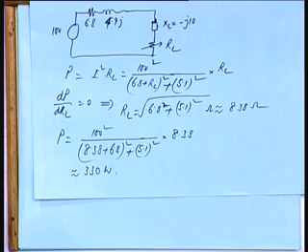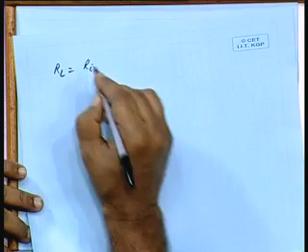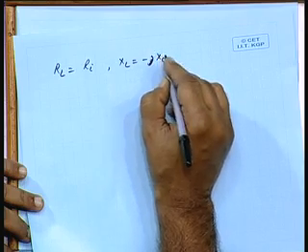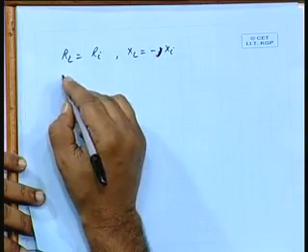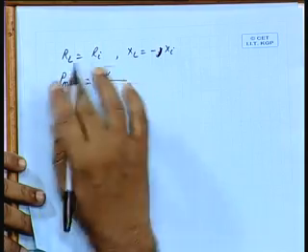Okay. And the last situation is when both RL and XL are varied, and all of you know, because this is the relationship that you normally derive in classes, that is what would be the maximum power transfer to the load. The condition is load impedance should be complex conjugate of the internal impedance. So, RL should be equal to RI and XL should be equal to minus of XI, J is implied. So, P maximum will be voltage by how much is the total impedance?